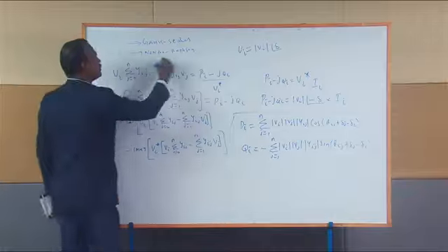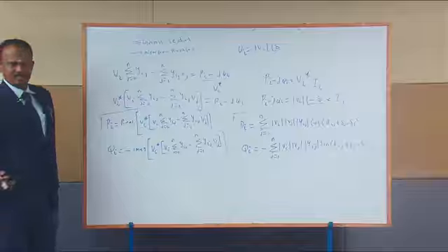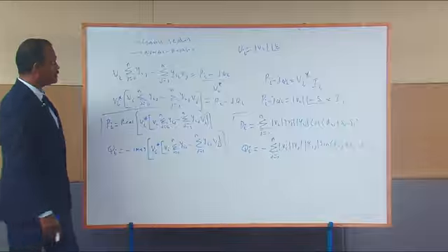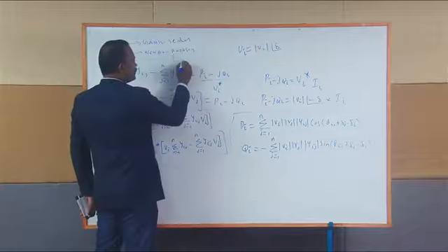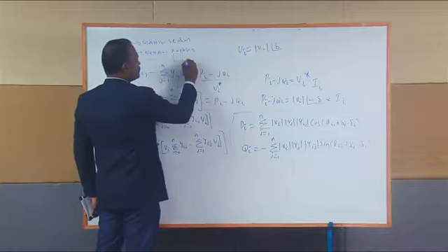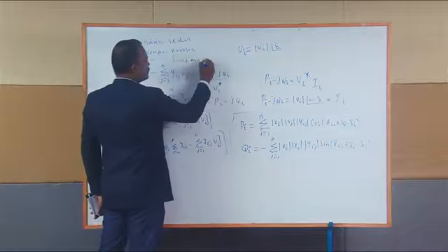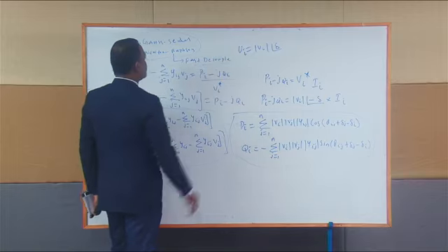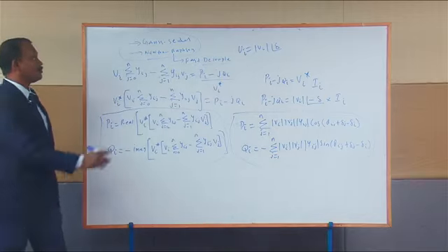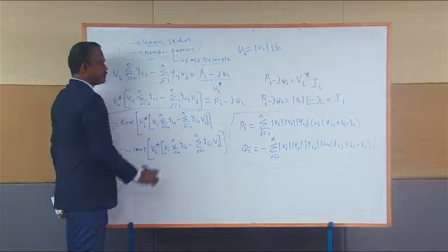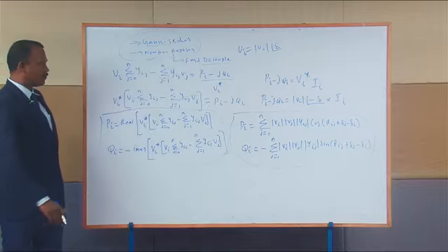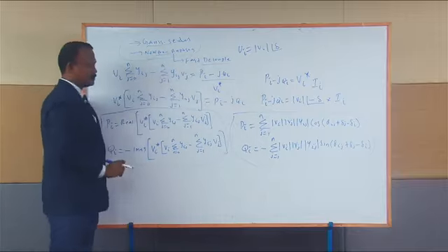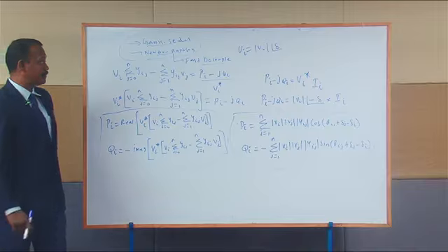These are the two important methods used for getting the solution for the power flow equations. The Newton Raphson method is again simplified as the fast decoupled method. Normally the Gauss-Seidel method uses the rectangular form of the power flow equations, and the Newton Raphson method uses the polar form.